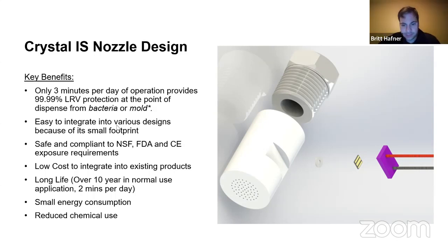Another couple questions rolled in. One is, what is the largest volume of water pipe size that this technology can be applied to? So like how large of a nozzle, I guess. Yep. So this is around a half-inch design. It really depends on the flow. The water flow is not as important a component as the diameter of the nozzle itself. So 3/4 inch could probably work, maybe up to 1 inch.